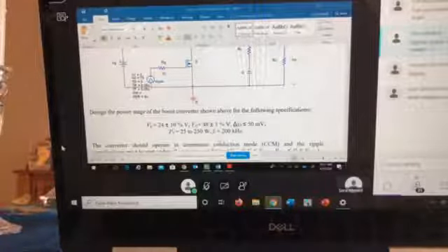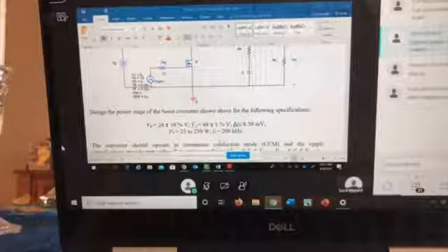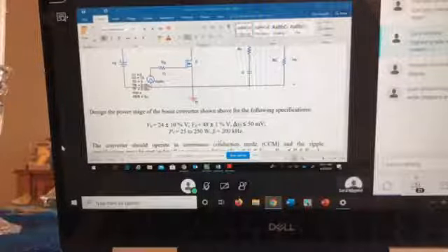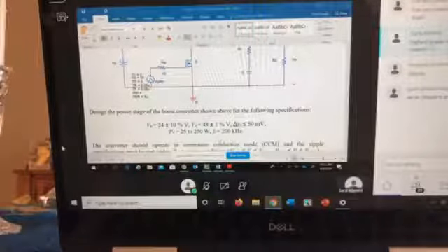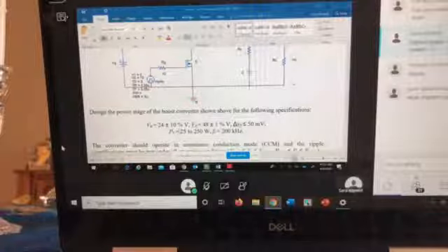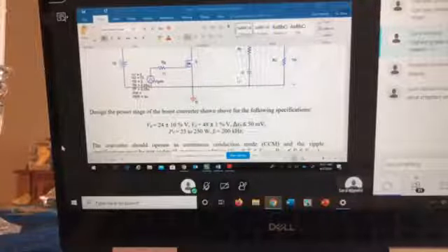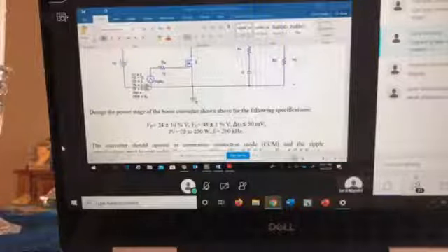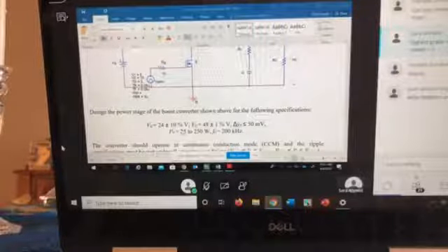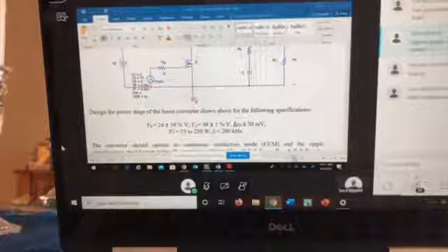So what is a load? A load can be whatever kind of load. Here we're just treating it as a resistive load, so you only have active power. How do you define this R? You define it by the percentage of the power, right? That's why I gave you the range here from 25 to 250. So you need to design a converter that can work when you have a low power or low load and a high load, right? Those are the two ranges here.